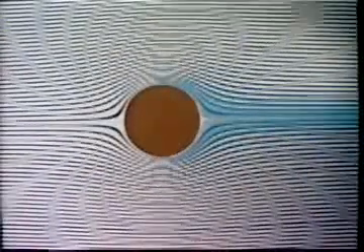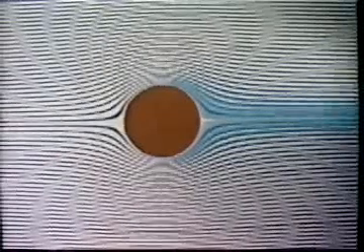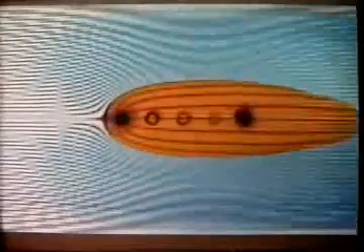When they are deflected by a thin disc placed between the sheets, they assume the same form as those of an ideal fluid when deflected by a cylinder of the same cross-section. Now, instead of a solid body, a source is started in the flow. Here is the flow round a half body. The red dye shows the internal streamlines. When the rate of fluid flowing from the source is constant, the streamlines are sharp.